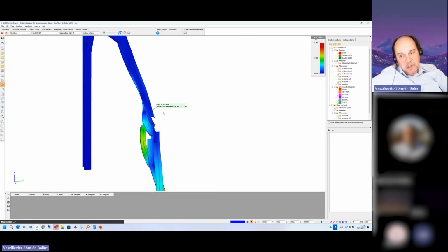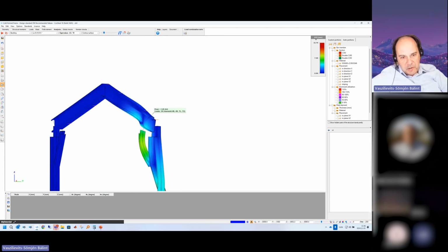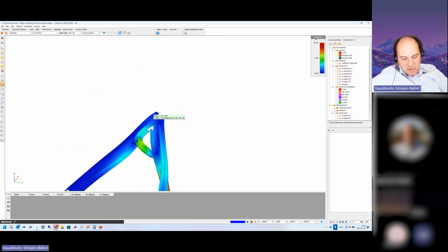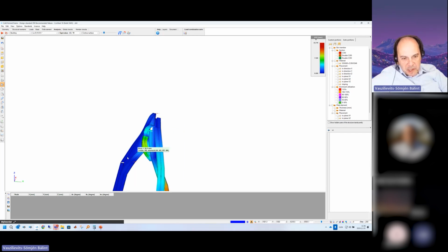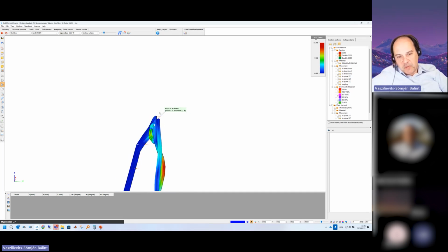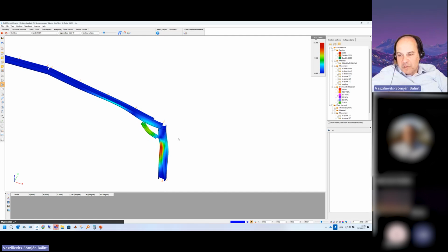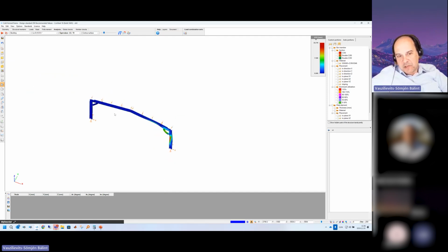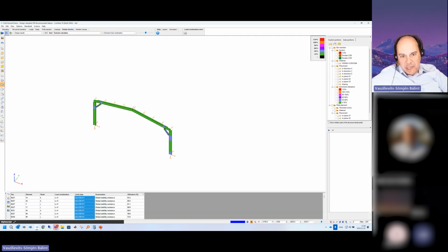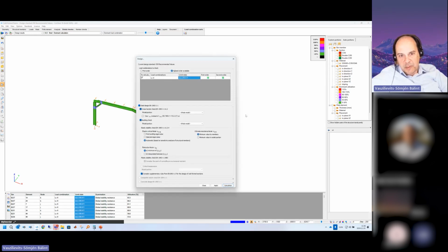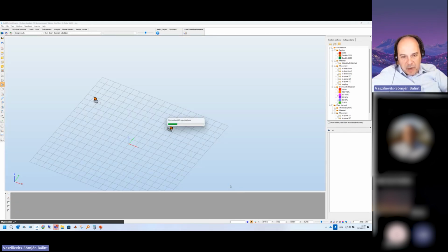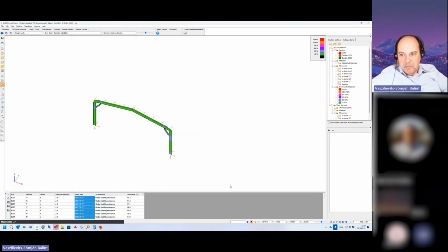This is now a buckling shape which is required for the stability calculation. What you can see is that the elements are continuing perfectly without any break, without any gap, without any discontinuity between the single and double member. This is proof that mechanically everything is perfectly and consistently transferred. And when we come to structural design, the whole thing becomes as simple as with the simply supported member. I just activate the buckling check and run the calculation. And if my results are below 100%, then I can be sure that the structure works correctly.